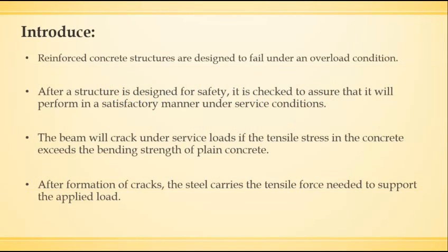Reinforced concrete structures are designed to fail under an overload condition. After a structure is designed for safety, it is checked to assure that it will perform in a satisfactory manner under service conditions. The beam will crack under service load if the tensile stress in the concrete exceeds the bending strength of plain concrete. After formation of cracks, the steel carries the tensile force needed to support the applied load.